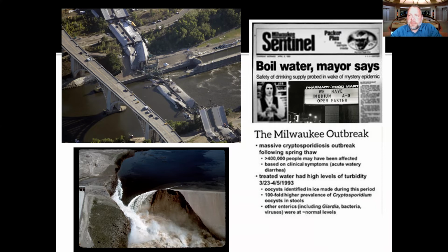They were not monitoring their turbidity levels post-filtration as well as they should have been. And you'll learn all about that in EGC 572, how to control filtration. But they weren't disinfecting properly, and this organism, cryptosporidium, and giardia are both very common, but because of their characteristics, they're hard to kill with disinfection. Very easy to remove with filtration because they're fairly large organisms, but they cause what's called hiker's diarrhea. If you happen to drink water when you're out in the woods and get diarrhea from it, it likely was caused by cryptosporidia or giardia.